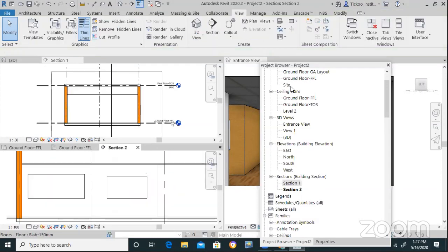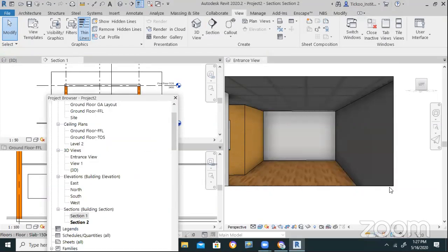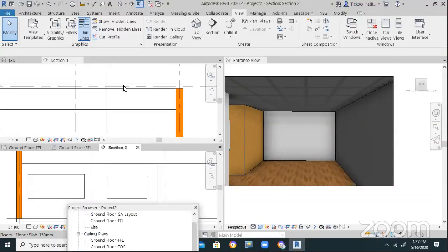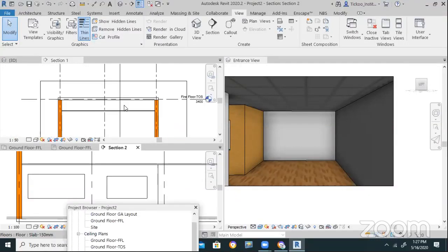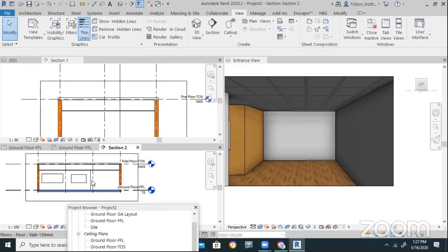Now you can see in the 3D view that all the partitions now go up to the ceiling part. Now you have got two parts. This part is called the plenum part, where the air conditioning ducts will be going, and this is the false ceiling part. Now I can do some detailing and a lot of other things.